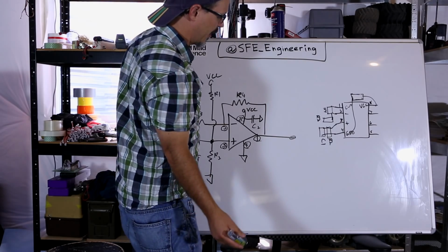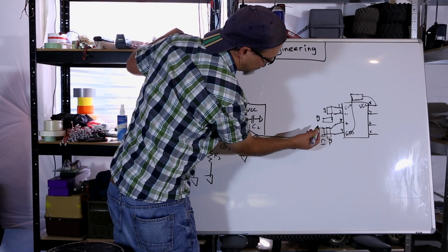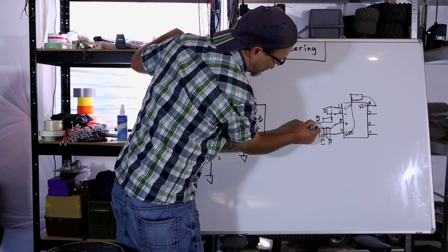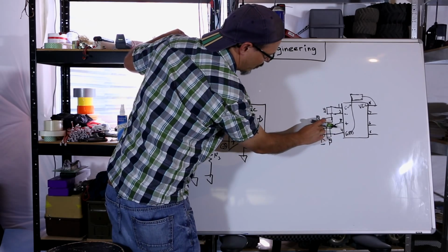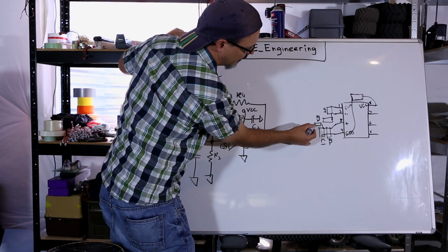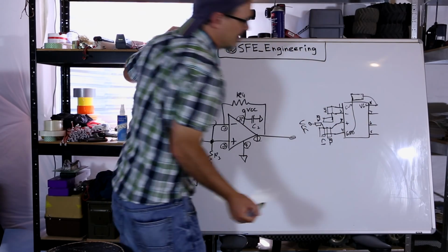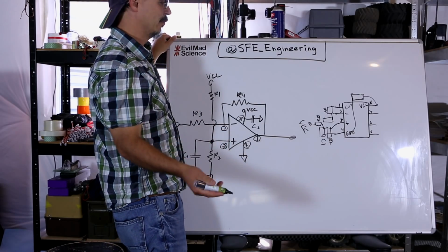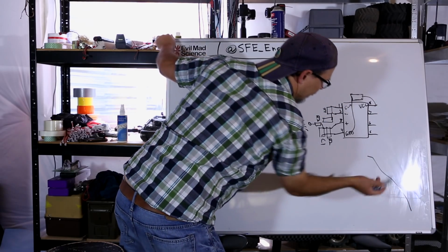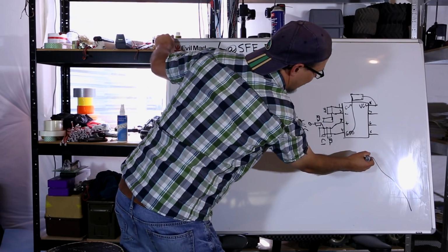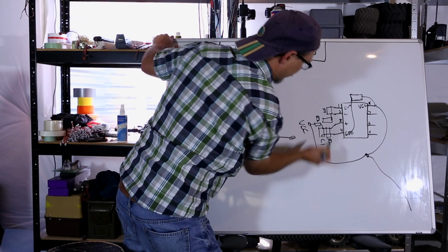Where would I put R1? Well, the best place electrically would be to put it probably close by in here so that you minimize that current path. And I probably wouldn't run it there. I'd probably run it to there. Then, of course, I've got to get VCC there and there. So I need 2 feed points. So what I would probably do on a PCB is I would string my trunk, arbitrary trunk, off to a single place and then run a trace up to here and a trace over to here, okay?